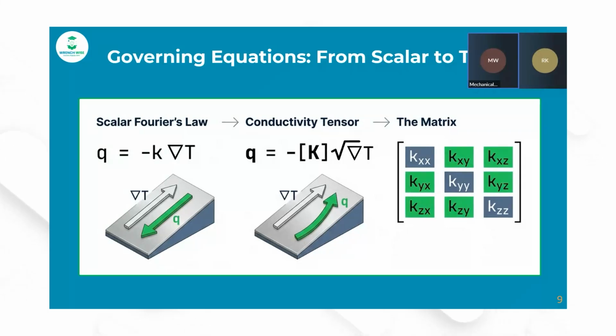That's the point. So in the matrix on the right hand side that you see here, the diagonal terms xx, yy, and zz define conductivity along your principal axes x, y, and z. In a battery, these are set to represent the high conductivity of the highway, the winding direction itself, and the low conductivity of the wall, the radial direction. Then the off diagonal elements here, xy, xz, yx, yz, zx, zy, are critical for high fidelity. They handle the coordinate alignment and vector rotation.